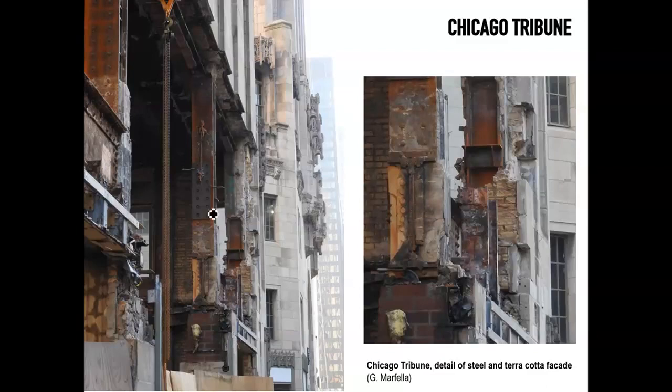You can see the steel members here with visible rivets. So you see steel columns, you can still see a girder here, which is combining a flat plate and angle plate, so not necessarily a continuous rolled beam, but a composite beam that is put together using mechanical rivets, possibly done in a factory.